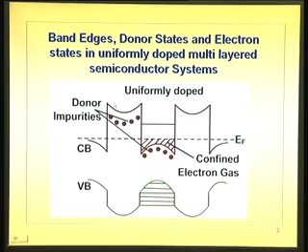This is a band edge, but here you are showing more than one. So, you have got multi-layered semiconductor system, like what we showed for undoped 1, 2, 3, 4. See 1, 2, 3, 4, 5 layers are there. Gallium arsenide, aluminum gallium arsenide, gallium arsenide, aluminum gallium arsenide, gallium arsenide.